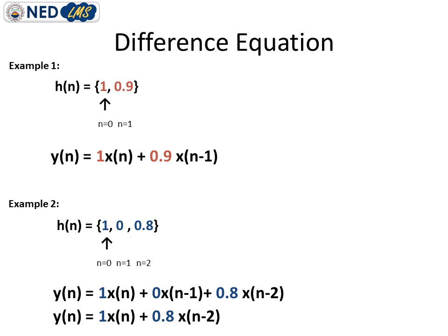This impulse response is denoting the system coefficients, and with the help of these coefficients we can write the system equation. Please remember that this is only true for FIR filters, for which the recursive part is equal to 0.